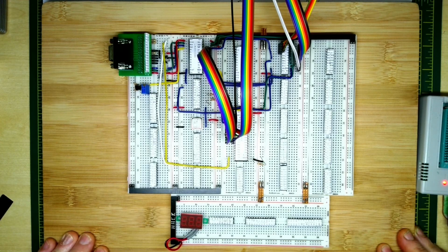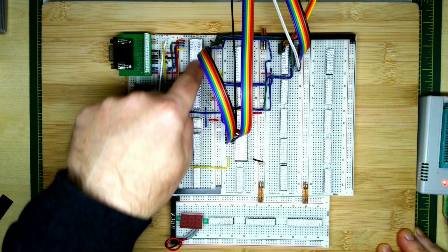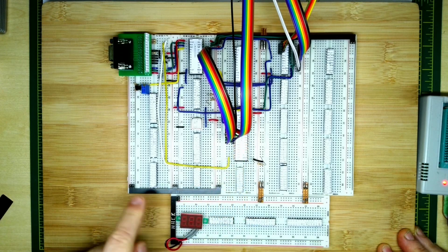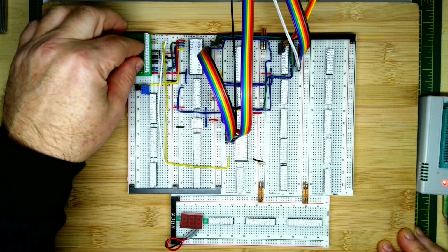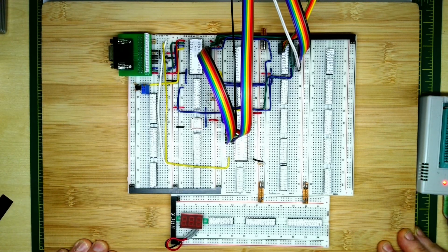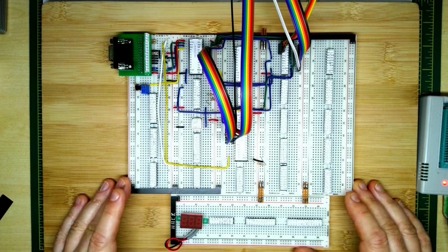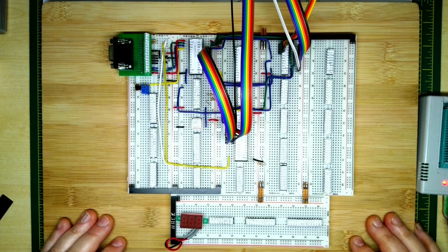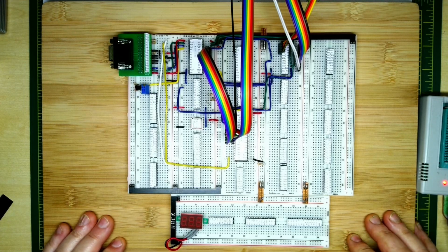We're also going to need to write the software to program the video DAC and the CRTC for the CGA compatible values. Now, we're not going to be able to use the values that are in the default BIOS, because although this is a CGA software compatible card, it produces VGA compatible output, so the timings have to be different. So in the next video I'll be plugging this into the main breadboard PC, and then we'll be writing the software to test this, or modifying the MDA video card software to run with this one, and then hopefully we'll be able to get our test pattern.